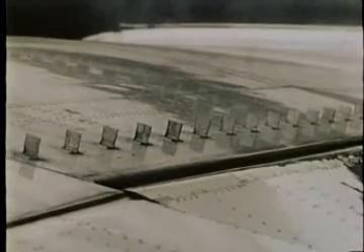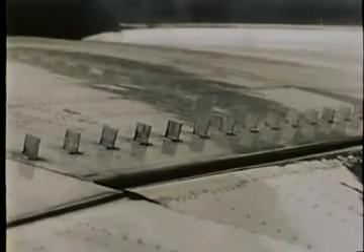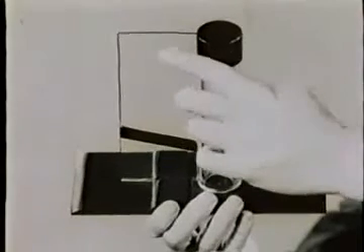In this film, we looked at flow along a flat plate and then saw the effect of pressure gradients on boundary layer flow. Now we can understand how this cylinder influences the flow on this plate. Without the plate attached, there is a static pressure increase along the stagnation streamline, with a corresponding decrease in velocity. When the plate is attached, a positive pressure gradient is imposed along the plate in the flow direction. This unfavorable pressure gradient causes boundary layer separation, and the flow field is radically altered.